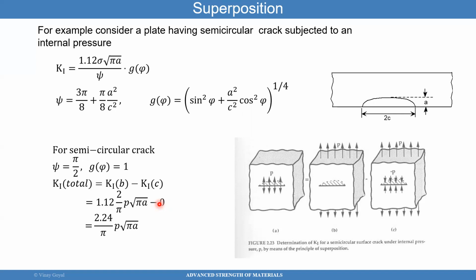Here's another example. Here what you see is an example where I have a pressure applied inside a crack. There are solutions for a surface crack with a far field stress. So if I want to study that, I can study this case, and there's a solution for this problem too, where you have a far field stress, but with a pressure applied in compression. It turns out if I subtract these two, I get this problem here because the pressure cancels out, and then you only get a pressure inside the surface.